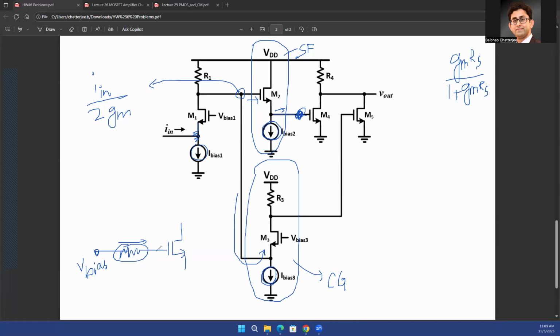So even though, let's say you want to apply V bias, what you're going to get is something a little lower than the V bias because of the voltage drop across the parasitic capacitance. Similarly, if you apply a V bias at the source over here, similar things will happen. You're not going to get the same bias that you intended because of all these leakage and parasitic components.